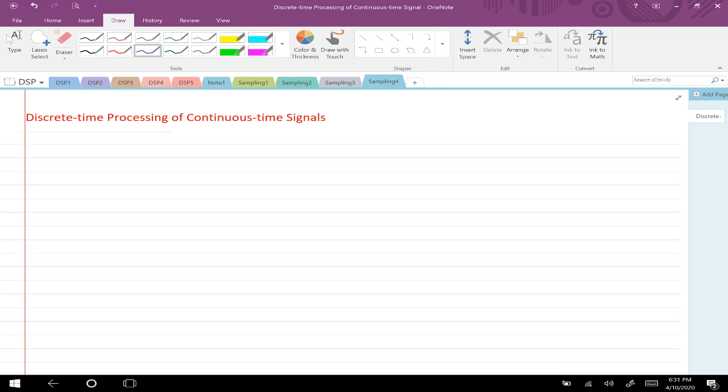Suppose you have a signal which is xc of t. This is a continuous time signal. You would like to convert that analog continuous time signal to discrete time. You write it as A to D, and this block is labeled with T. Notice that by the A to D converter block, we are representing both the multiplication with an impulse train as well as the integration part, everything. So as if the output now is simply x of n. That's what you got from there.